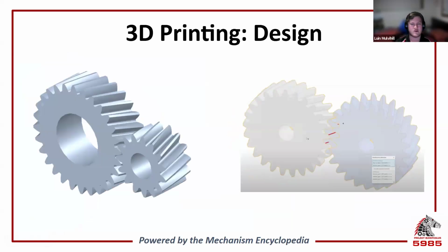So to reduce the amount of pressure on each tooth, we can use a helical gear. Helical gears have teeth that are slanted at an angle, commonly somewhere between 15 and 25 degrees, and that's the helix angle. Because of this, the meshing of the teeth occurs gradually instead of all at once like with the spur gear, and there is more than one tooth, usually 2 or 3, in contact at the same time, which distributes the load more evenly between them.